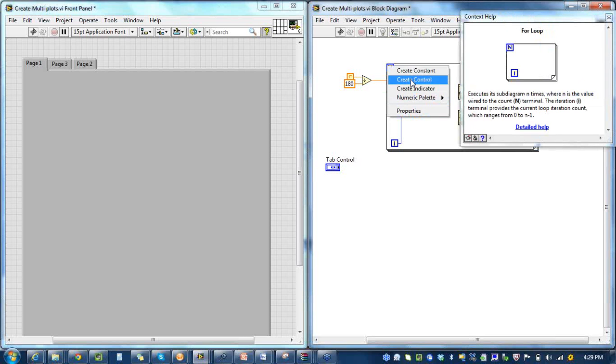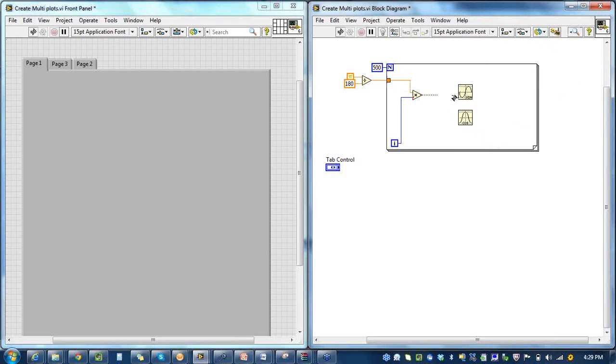So I'm converting my degrees to radians here. Let this run for about 500 samples. Okay, now I'm going to give this to my sine and cos. Like we saw last week, to create an array programmatically, you can simply wire this to the border of your for loop, and this auto-indexes it, thereby giving an output array of all data points for every iteration of the sine value.